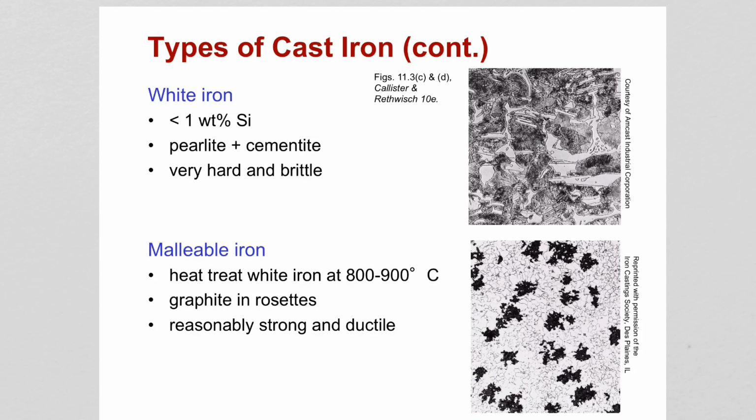This structure, because it has cementite, is brittle and very hard. This is a virtually unmachinable alloy because it is very brittle. Therefore, its application is limited to applications where you require a very hard and very resistant surface, but do not require a high degree of ductility.